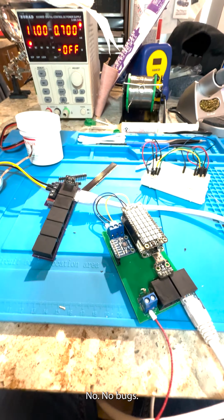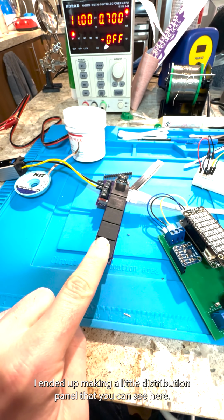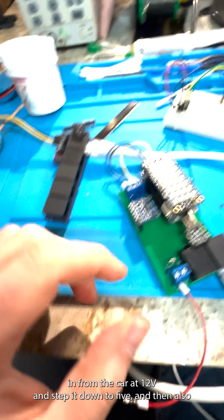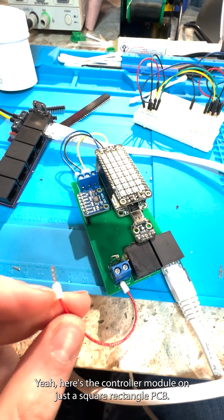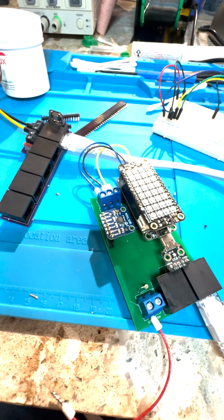No bugs. I ended up making a little distribution panel that you can see here. It's got a fuse in line, and it allows me to take power in from the car at 12 volts and step it down to 5, and also do some distribution stuff so that it's technically a CAN bus. And here's the controller module on just a square rectangle PCB. It's got a button.